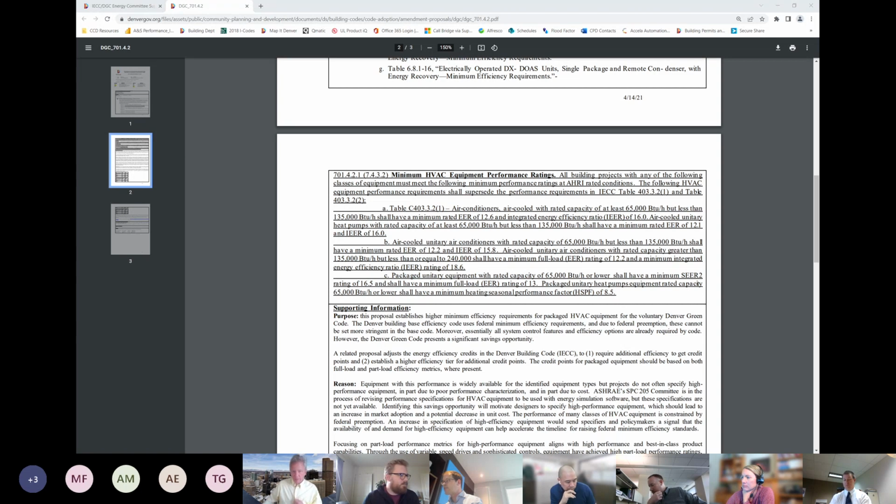Elizabeth, you asked, does it really mean package? I get into, and actually Mike gets into, a lot of custom equipment. And when we start talking custom equipment, we're definitely coloring outside the lines. We're still obligated to meet the base code. It's more interesting in the green code, but in the base code, we're still obligated to meet those minimum IEERs and EERs, even with custom equipment. The interesting thing is it's just not, quote unquote, certified. I believe that the intent here is to stay within the lines of certified AHRI equipment, which essentially by definition means package. There's a catalog to it.